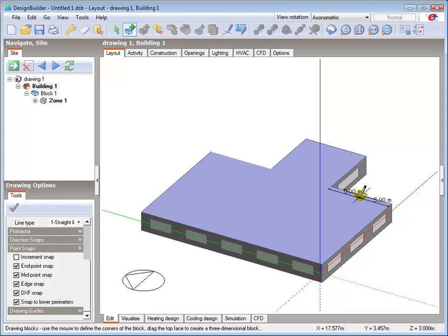Note that the cyan colour appears green here due to the highlighted cursor. Keeping the Shift key depressed, locate the desired snap point and left click to start the block. Once you've entered the start point, you can release the Shift key and continue to trace round the block using the end snap points.